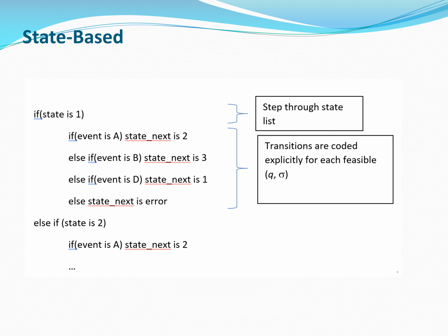Our first design pattern is state-based, and in this approach, using a switch case or the if-else structure, we organize the state machine about the states, and then for each state, we check for each of the feasible events that corresponds to that state, and then set the next state based on the possible event.